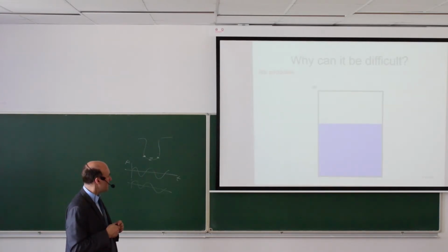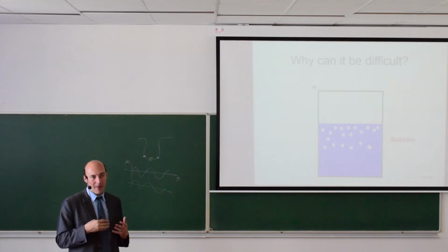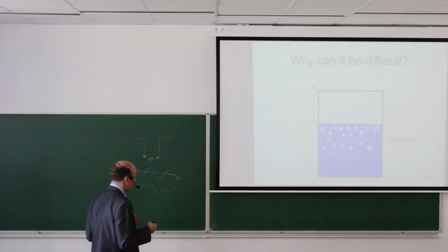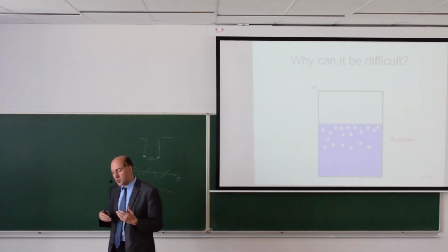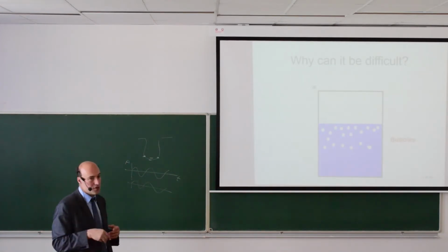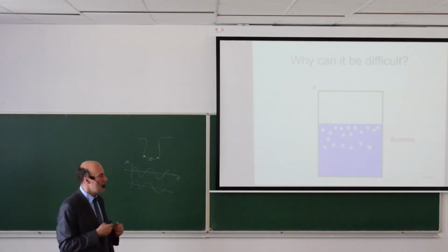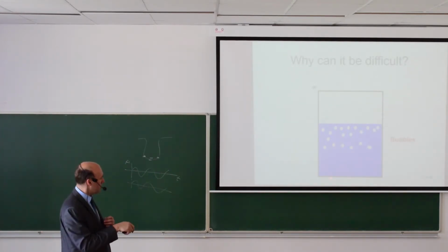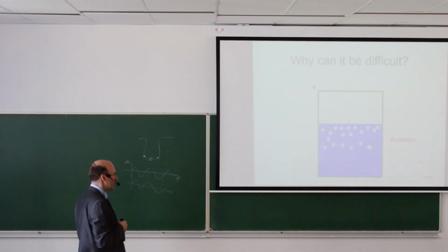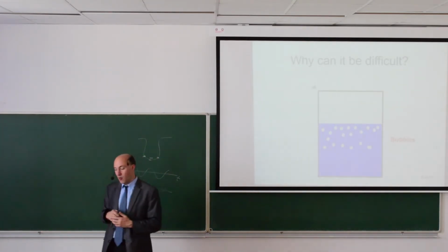If we look a little bit more at what can happen in the process, we can have a liquid, and when this is just a liquid without any mixing, then no problem at all. But we can add bubbles. It can be a mixture of water and carbon dioxide, for example. So we will have bubbles, and those bubbles can prevent some sensors from working. For example, if we would install an ultrasonic sensor from the bottom here, then we will not have a clear reflection from the liquid level, but this ultrasonic signal will be blocked. So bubbles can be a problem.